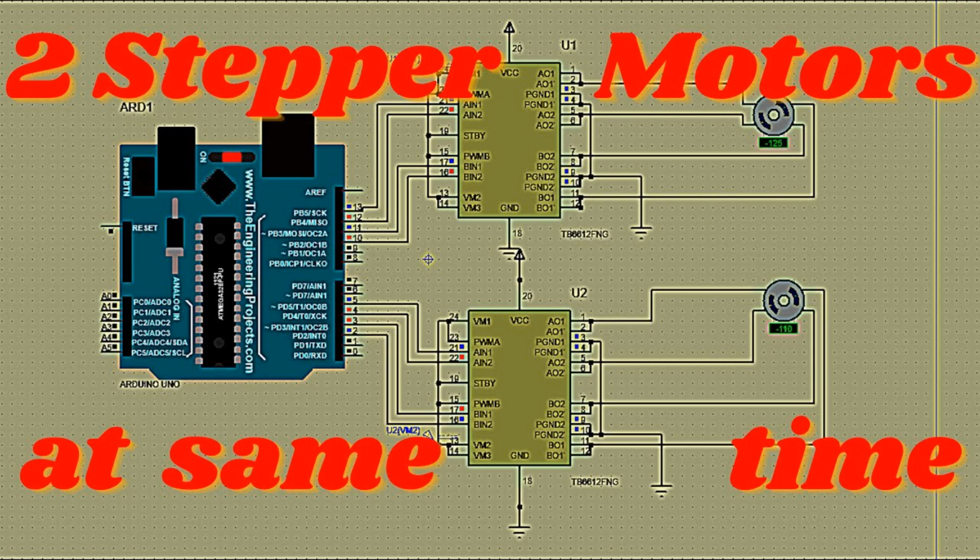Universal motor drivers are used to control universal motors, which are a type of electric motor that can run on both AC and DC power sources. Universal motors are widely used in applications requiring high starting torque and variable speed control, such as in household appliances, power tools, and small appliances. Unlike AC induction motors, universal motors have a field winding on the stator and an armature winding on the rotor, which allows them to operate on either DC or AC power.